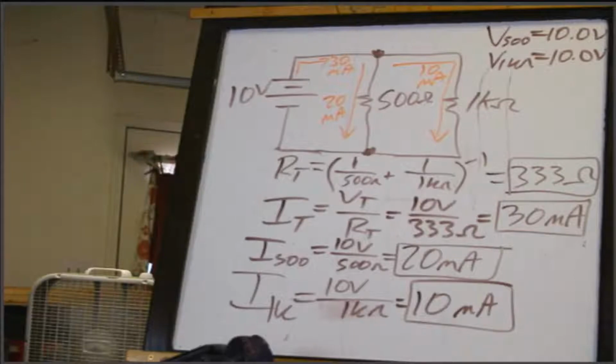Yes, John, correct. All right. You can see, with series circuits, we said that because it's directly proportional, if they have a higher resistance value, they have a higher voltage drop, right? Well, with parallel circuits, the lower the resistance value, meaning there's less effort to stop the current, the more current you have, because they're inversely proportional.